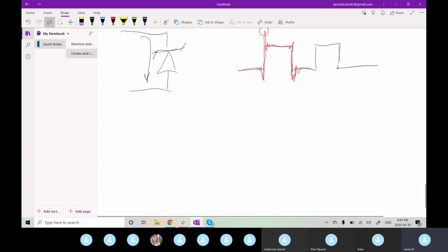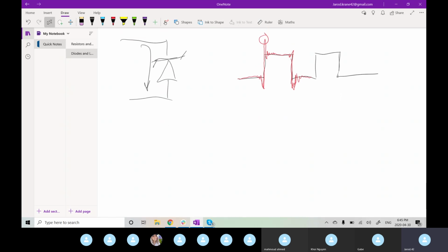Or in the case of ESD, or electrostatic discharge, which can be a few thousand volts, and can come from just human touch. If you're just touching the pins, unprotected, ungrounded, if you were just to go up and poke a pin, you have enough static charge in you at times to potentially induce these high transient voltages into your system. So you can cause these peaks and destroy your system.